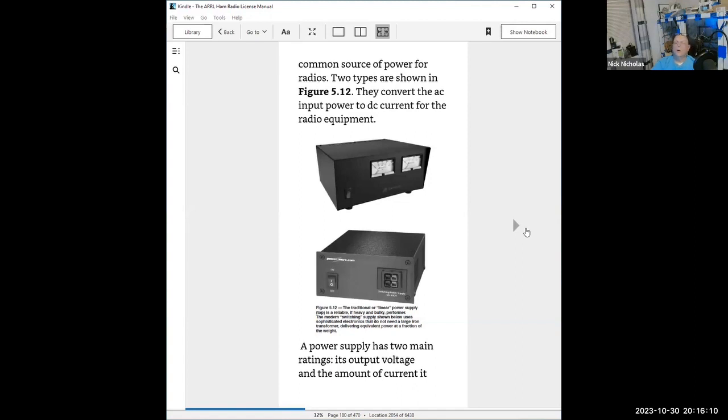The reason digital power supplies can make noise is because they sample by switching on and off. And by switching on and off very rapidly, they're an oscillator. They create harmonics. They create RF noise. The better the quality of a digital power supply, the better the filtration. Some of them today are so good, I wouldn't hesitate to use them, but there are a lot of terrible ones out there.